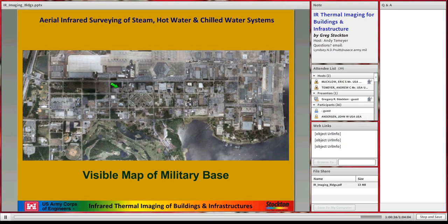You know, if it's 80 degrees outside and it's 76 degrees inside, you're going to have a pretty miserable survey. Now, you need a more sensitive camera to be able to do that kind of work. So I recommend to the man or the lady in Hawaii that they take that into consideration when buying an infrared camera. Get one that has very, very low sensitivity, like 25 millikelvin, because you're going to deal with it when you're looking at buildings in Hawaii, I'm sure, because you don't get the extremes like you do in the Northeast and the Midwest and the rest of the country.